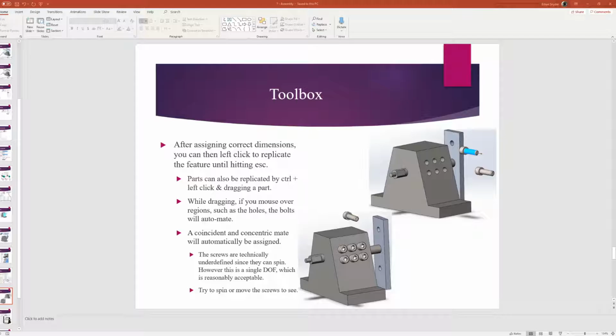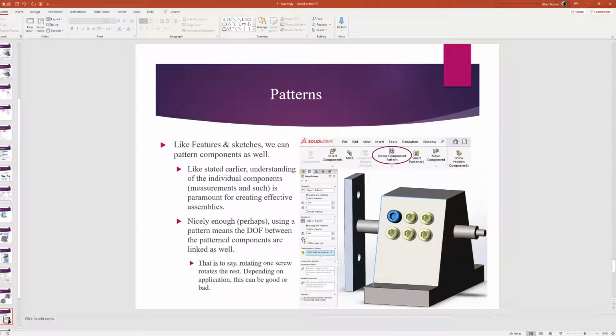So now it's not actually where it should be. However, I'll assign this mate, and I'm actually going to move it up a little bit more and then say, hey, you, go with you. Now if I hit OK, we'll notice that it will be able to rotate, but I can't pull it out anymore. It's locked in place against that surface.